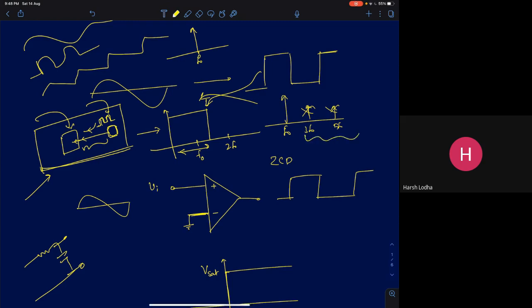Let's assume this low pass filter can be approximated as a brick wall low pass filter, shown here. This is the frequency response of a brick wall low pass filter. I'm approximating this RC circuit's frequency response. It's a very crude and bad approximation, but for argument's sake, we're just going to use it. If you pass a square wave signal through this low pass filter, let's assume your fundamental frequency falls within the cutoff frequency. This fc is the cutoff frequency here. After that, the gain is 0. The low pass filter doesn't pass any frequencies at all.